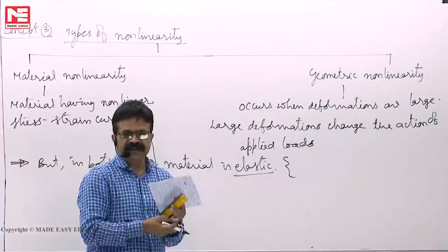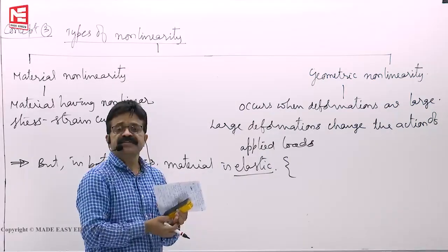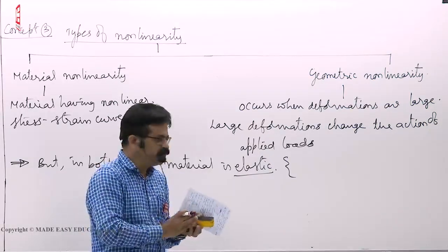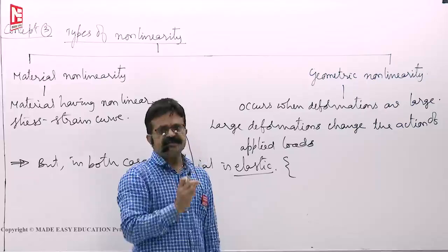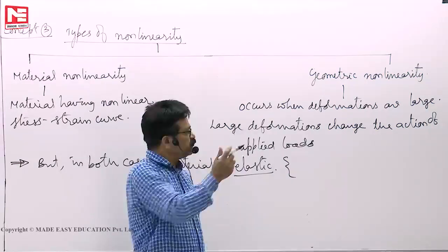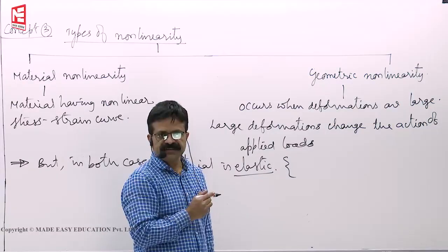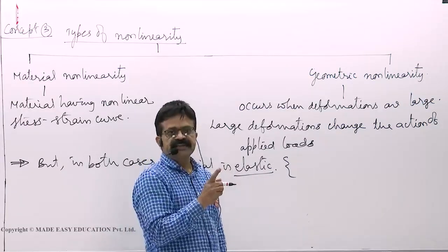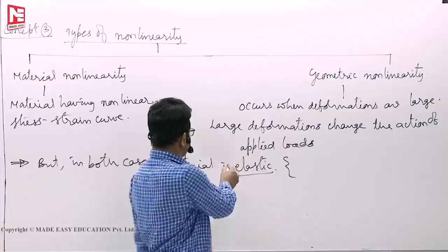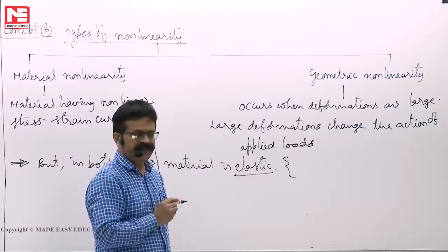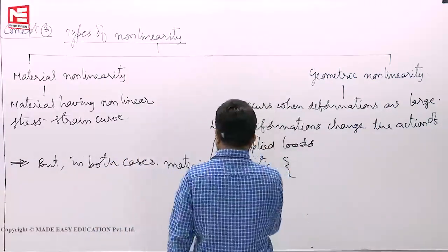Engineering mechanics sir might have told you, law of conservation of energy is applicable only when you have perfectly elastic materials. So, for the energy theorems, where you use the law of conservation of energy, for those energy theorems to be applicable, they must be elastic.